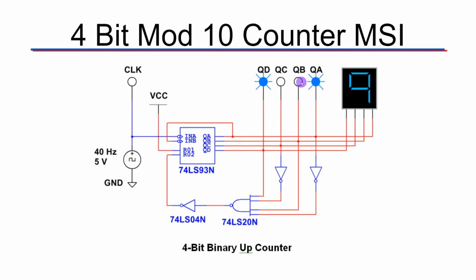And using a 4-bit counter, we could actually go right through a whole hexadecimal unit, from 0 to F, or the equivalent of 0 to 15 in decimal. And so what we're doing is specifically enabling logic here so that instead of continuing on a normal synchronous count, when it would otherwise go to a number that we don't want to display, it's actually going to toggle the reset for the entire 4-bit counter, which is the equivalent of toggling the reset for each of the 4 provided flip-flops. All these signals will be reset when we toggle that value.